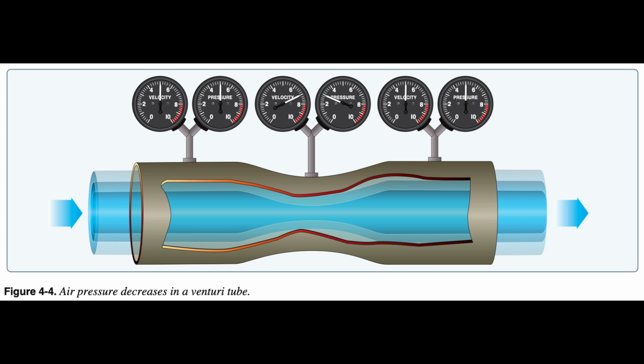Since air is recognized as a body, and it is understood that air will follow the above laws, one can begin to see how and why an airplane wing develops lift. As the wing moves through the air, the flow of air across the curved top surface increases in velocity, creating a low-pressure area. Although Newton, Bernoulli, and hundreds of other early scientists who studied the physical laws of the universe did not have the sophisticated laboratories available today, they provided great insight to the contemporary viewpoint of how lift is created.